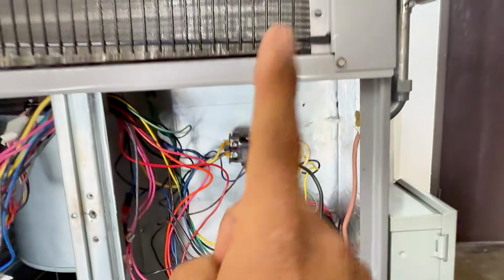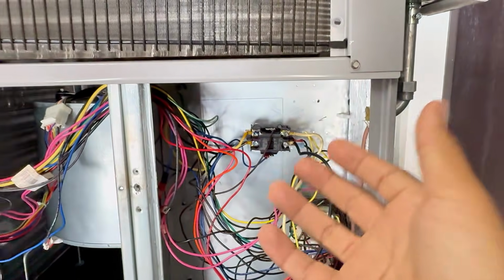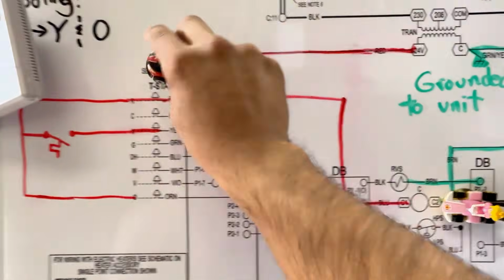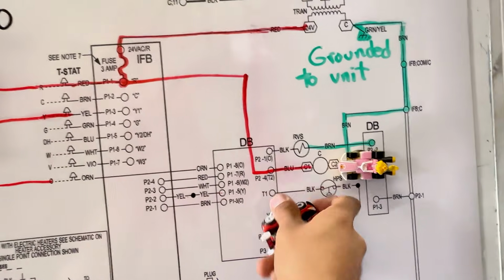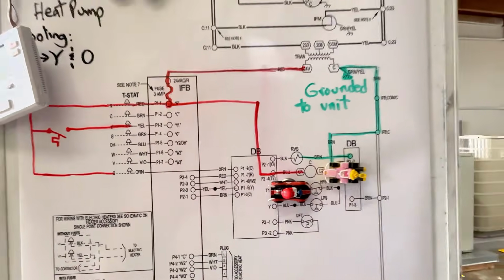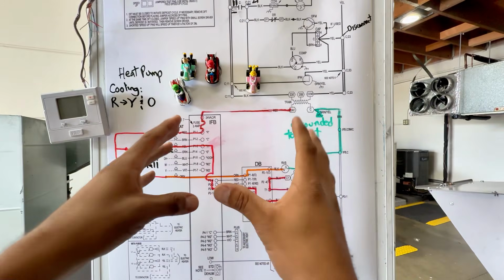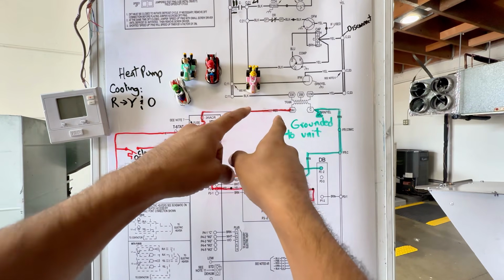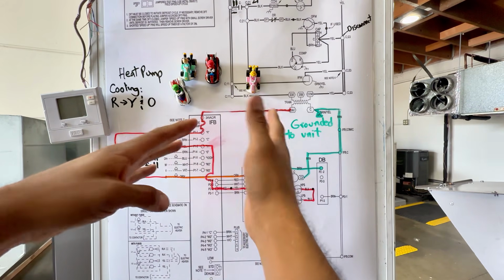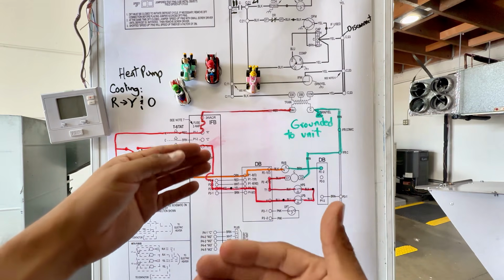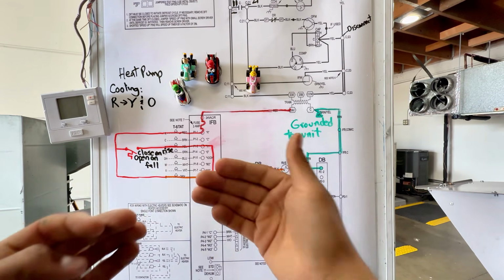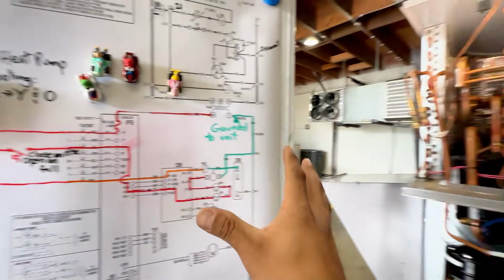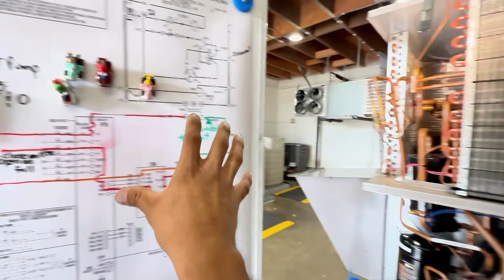So now we are going to do it the right way, and really pay attention to the journey that Mario takes to make it all the way to the other side of the coil. I do have it wired up the right way, in the sense that we're going to give Mario the correct path to take through the safety switches, pressure switches, and temperature switches, to make it to my contactor coil. And I'll show you on the actual unit how that is being done.